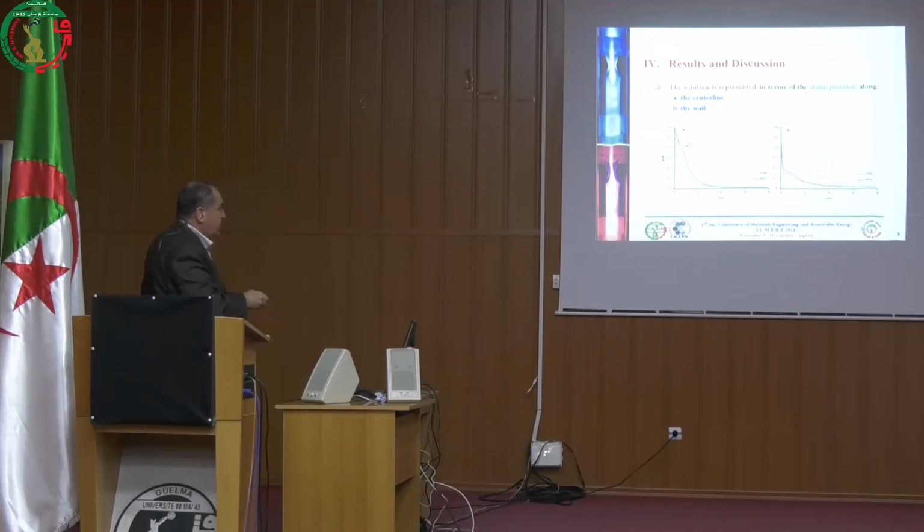In this case, we have a drop of the pressure, of course, because if you drop the pressure, the velocity will be higher, and then the Mach number will be higher. That is what we are doing, expanding the flow. The blue is the results coming from the method of characteristics, and the red or something like that is coming from the finite volume method.